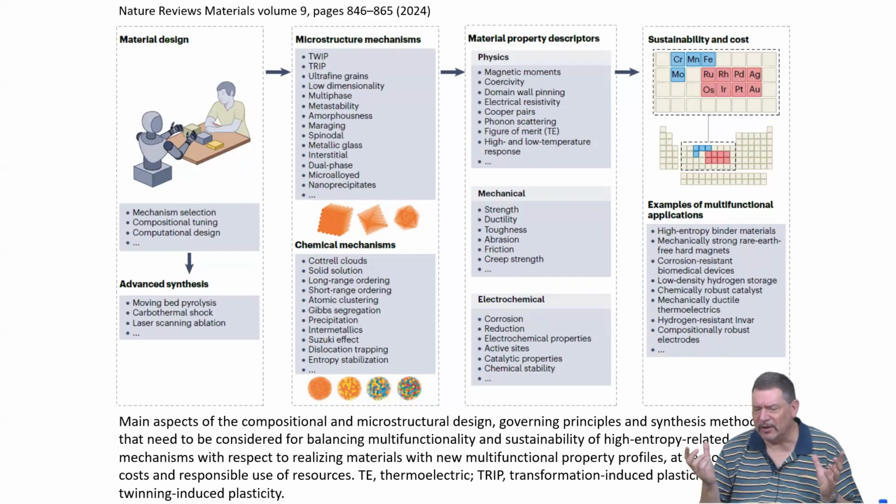But you also have to think of all these different aspects of, do you want to have a material that specifically absorbs stresses? So you want to have maybe TRIP or TWIP effects installed. Maybe you want to recycle the material, so chemical aspects come into play. Maybe the material should have ferromagnetic properties because you want to make a switch. And all of this really needs to go into your thinking and into this chain of thought in order to do materials selection and materials design. And this is the same for high entropy systems.